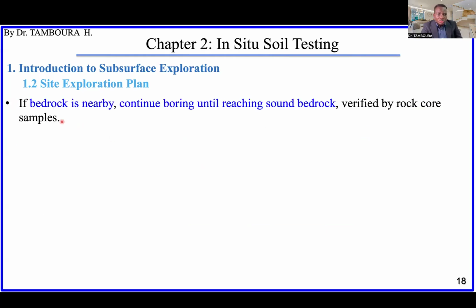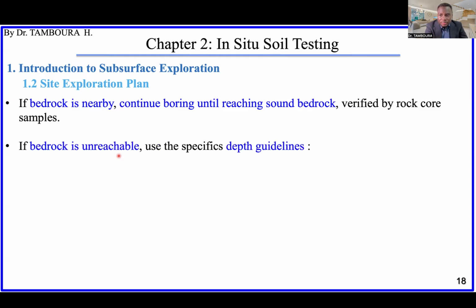So if the bedrock is nearby, just continue boring until you reach the sound bedrock. Verify by the rock quarry. And even in that case, you remember you need to go at least 3 meters in this, according to the Federal Highway Administration. If then you don't have bedrock nearby, or if it is unreachable, there are some specific guidelines for choosing the depth.